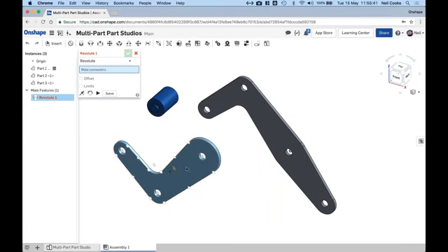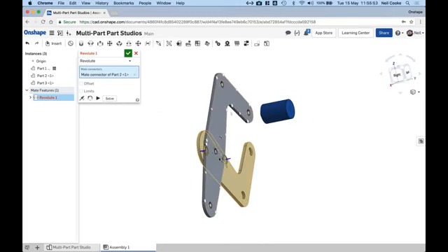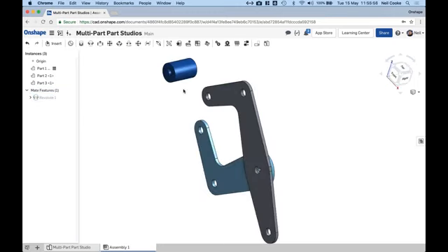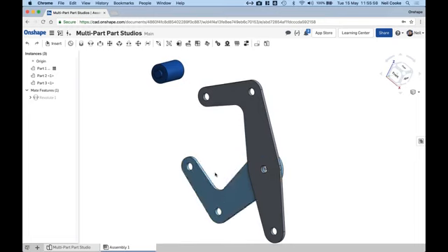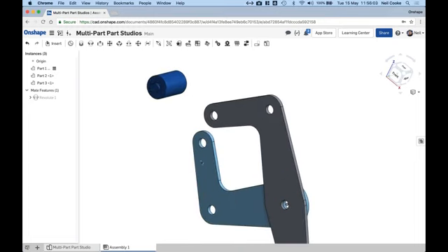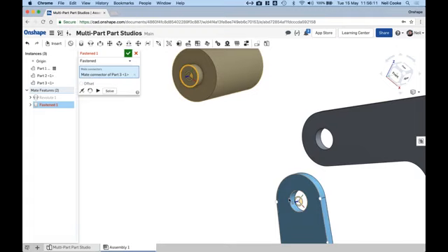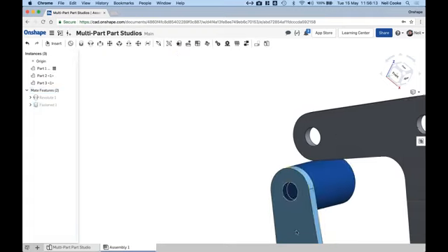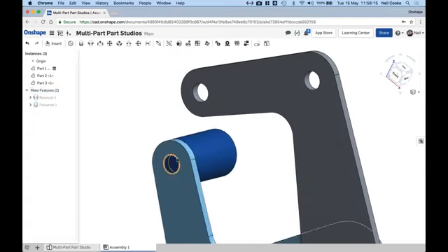So we'll just do a revolute mate, and as you see, as we hover the mouse over it, certain areas of the geometry highlight: center of holes, vertices, center of faces, and so on. So I want to create a revolute joint between that face there and that one there. So that's going to give me the motion that I need with one single command. Okay, and likewise then, this one over here, I could have grouped these two together first, but if not, I can simply just do a fasten mate between that hole and that hole, and then these two are going to be fastened together.